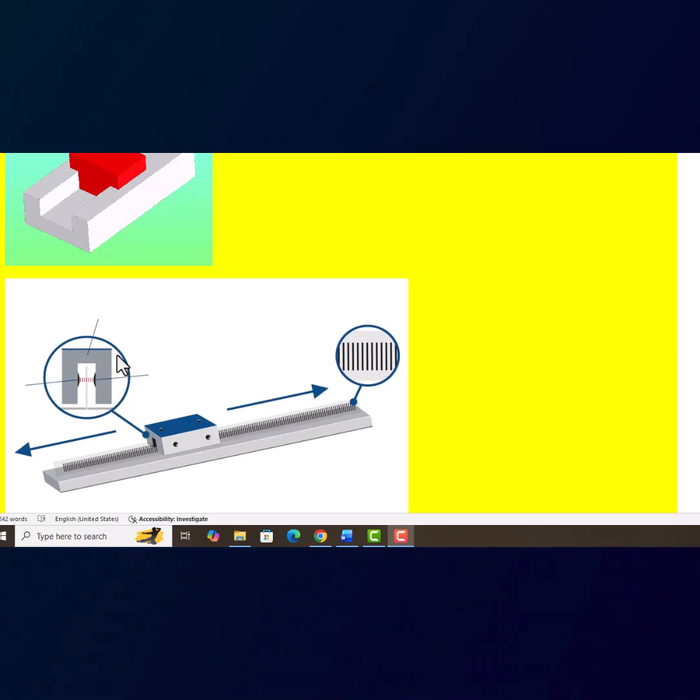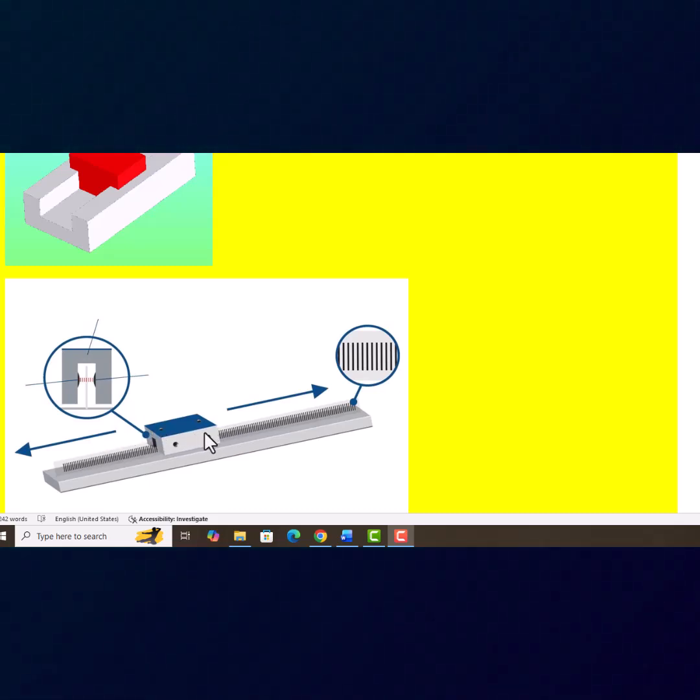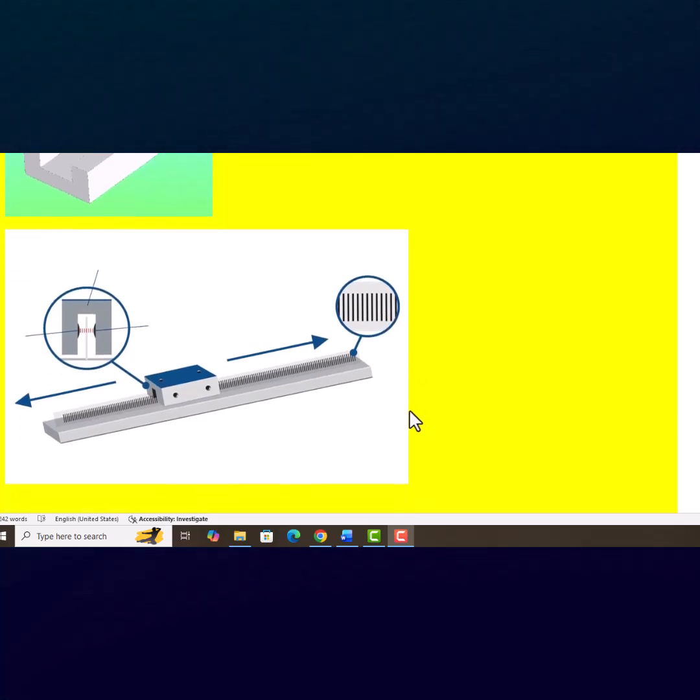One corresponds to phase B, the other corresponds to phase A. And this is the reference position of the joint. If the joint moves to the left, it produces the pulses. Similarly, when this joint moves to the right, the photodiodes will also produce the train of pulses.